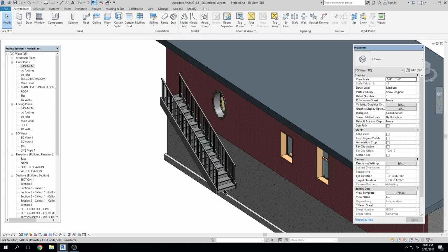We define the parameters. Essentially like walls and doors and floors, we have a stair type, just like we have a floor type or a wall type. Within the stair type, we have an assembly of sorts. But instead of it being gypsum board on both sides with a wood stud in the middle, you're going to define the parameters for the stairs. You're going to say these stairs are going to have a wood riser and a wood tread, and they can be no taller than 7 3/4 of an inch, and they're going to be 5 feet wide. You define all those parameters within your stair type, just like you would define the assembly of your wall within your wall type.